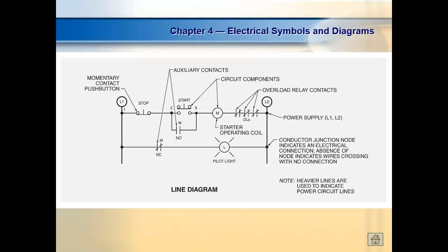This is a magnetic motor starter, and I know it's a motor starter because it has overloads. Did we talk about that in this class? Okay. So what's the function of the overloads? So this motor here, where's the stator at? This is a little single phase motor, and I can't put my camera up, so I just have to pass it around. This is the stator, and this little red thing right here is the overload. It's single phase, so all we have to do is just break one side.